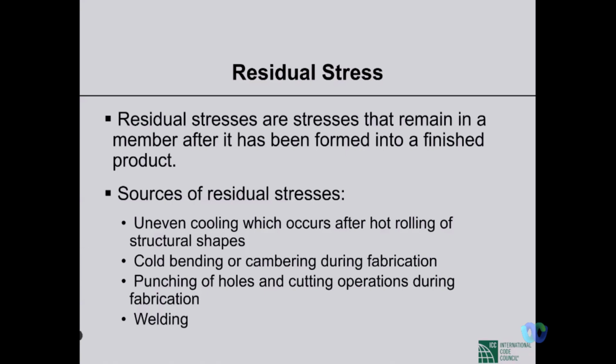Second is cold bending and cambering during fabrication. Once we bend something and keep it like that, that causes stresses to be trapped inside in those locations. Then punching of holes and cutting operations during fabrication.